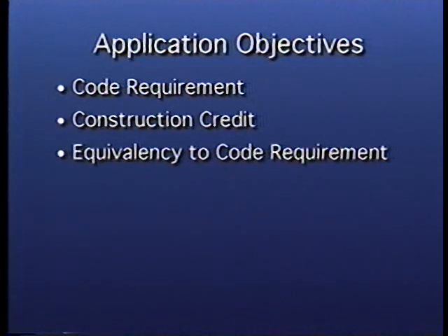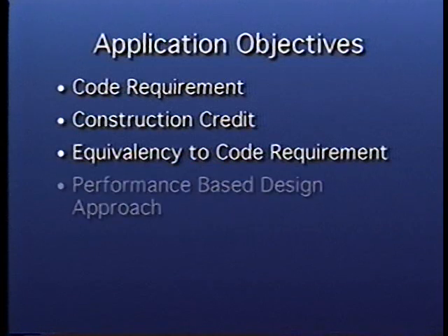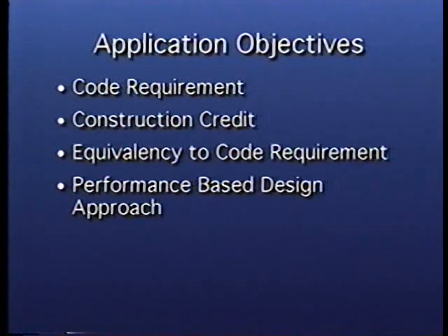For example, installing a non-required sprinkler system or enhancing a code-required system may be part of a performance-based design approach that will provide the desired level of overall protection. Examples could be to allow more open and interconnected levels in an atrium when an enhanced sprinkler system is provided, or allowing exposed steel structural elements to be protected by automatic sprinklers in lieu of fireproofing.